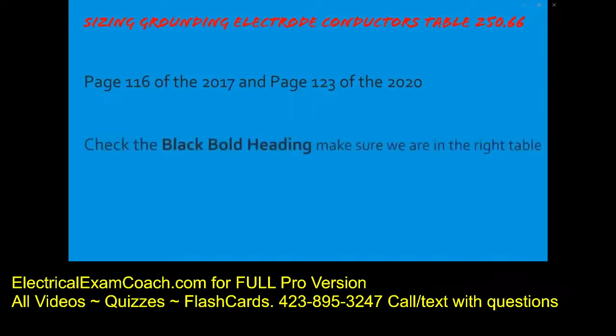Let's learn about sizing grounding electrode conductors. Everyone head to table 250.66. It's on page 116 of the 2017 and on page 123 of the 2020. Pause the video now if you need to. So the first thing we do there is we check the black bold heading and make sure that we're at the right table.